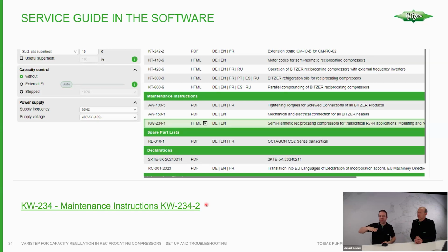Because if this is going, let's say, from 5 volts to 10 volts and it's dancing up and down, jumping, then the controller cannot react, or the IQ module cannot react perfectly on this, because it also needs a stable signal, and not saying I need 70%, I need 10%, I need 100%. So checking the 0 to 10 volt signal is also an important thing.